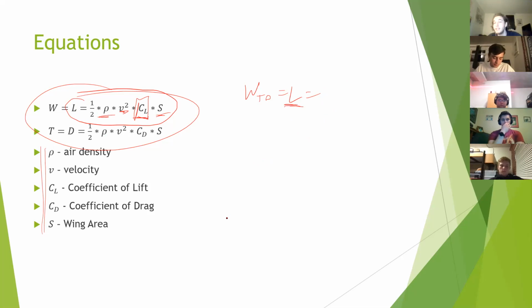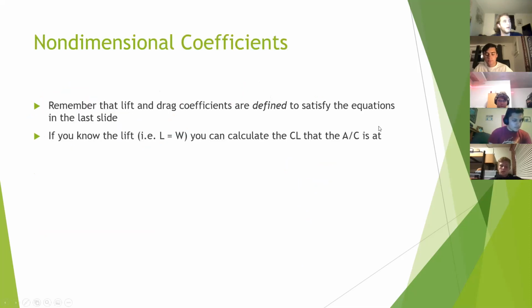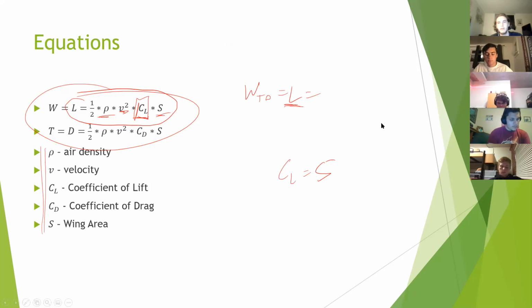Now, if you then get a CL that is 5, then you know that you just can't fly in that condition, right? You can't fly a 55-pound plane at 10 meters per second. I don't know why I switched to metric. With whatever wing area, you just can't do it. That is kind of dependent on your airfoil, but there are some decent assumptions you can make for quick modeling for a CL max. But yeah. Any questions on that? Okay.